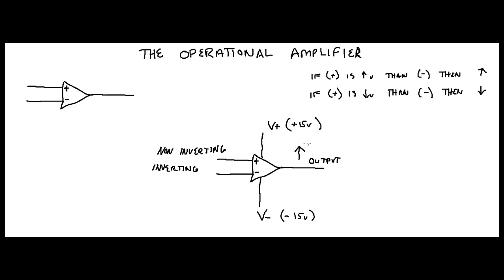So it's going to saturate to a level below your power here, your 15 volts. Usually it's around a volt or so. It depends. You could measure. You're going to measure it probably in labs you have. But I'm just going to call this plus 14 volts.